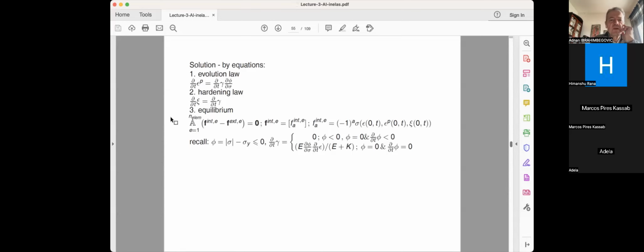So now we want to solve this set of equations, which is here: two evolution equations for each and every Gauss point where the element plastifies, and the set of global equilibrium equations, implicitly. Now, the trick is as follows. These two equations are local equations. They just concern the particular element which plastifies, not necessarily everywhere. Whereas this equation is a global equation, and it's certainly much more costly to solve and to handle.